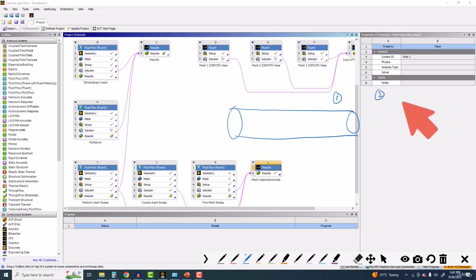The second case is that we can use the benefit of symmetry. So I can make it 180 degrees, or I can make it 90 degrees. Let's run one case with 180 degrees, only half. In the third case we will run the 1/4, and in the fourth case I will take one sector that is going to be 30 degrees.